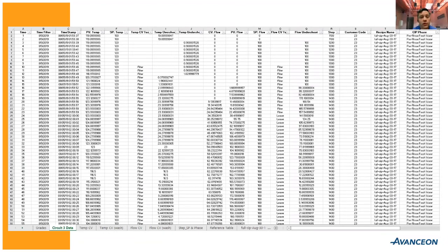And so we're able to do that through a couple of different ways. One, on our side, we're able to do things like event identification. So really making sure that we're targeting specific instances and moments in time based on what's happening inside the process. And then also data scrubbing. So making sure that any operational or physical mishaps, you hit an e-stop or a transmitter fell off or whatever, you don't want that kind of thing to skew the data and skew the results. Right. So making sure that's all cleaned up.